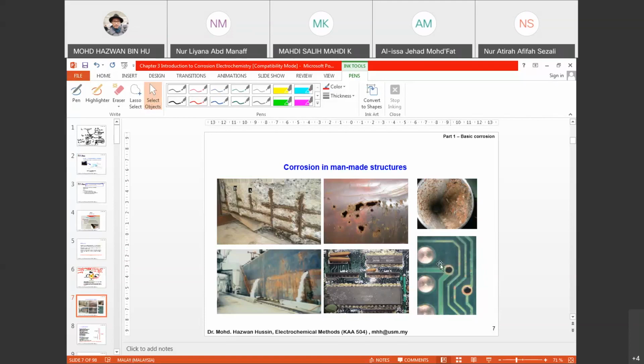Can we name that electrical corrosion? Yeah, this type of corrosion happens in electronic devices, and that's part of the example that you can see. So when you have corrosion on the contact, that is why when you press the button, it's not going to function because it has already become resistant. Okay, it's already forming metal oxide, so it's quite resistive. Then it cannot give a good connection or conductivity.